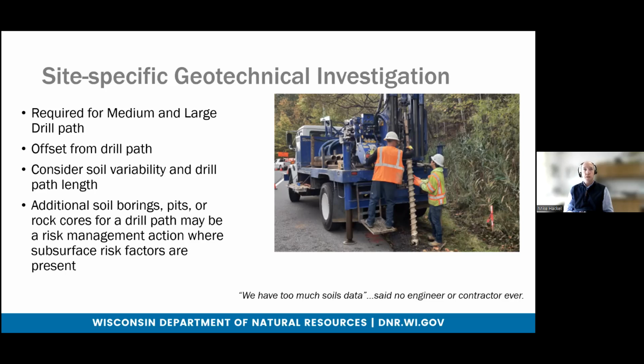And we'd want to make sure, understanding that when we're doing these borings, if we encounter soil types that are going to be challenging for the HDD, we may want to do additional borings to further understand what those soil types that we're investigating are. And as the quote there says, we can never have too much soils data when we're talking about working with underground and interacting with the soils.